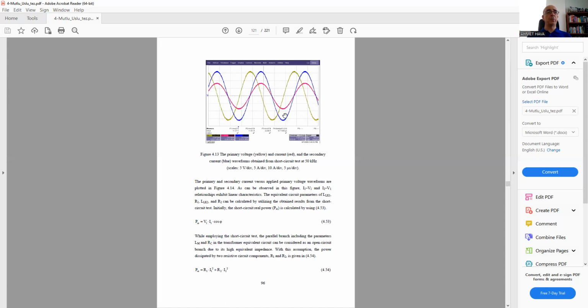So if we are measuring quantities, as a person who looks at the graphic and tries to understand, we want to know what is the square in terms of microseconds or milliseconds, whatever. In this case, it is illustrated as 5 microseconds per division.